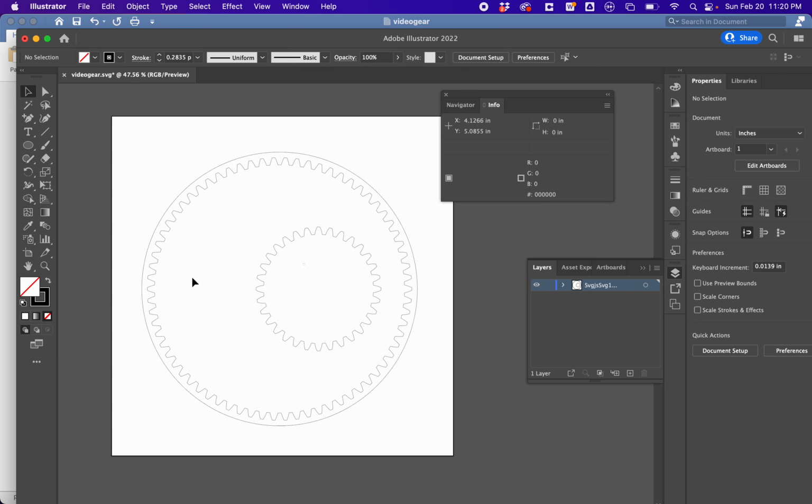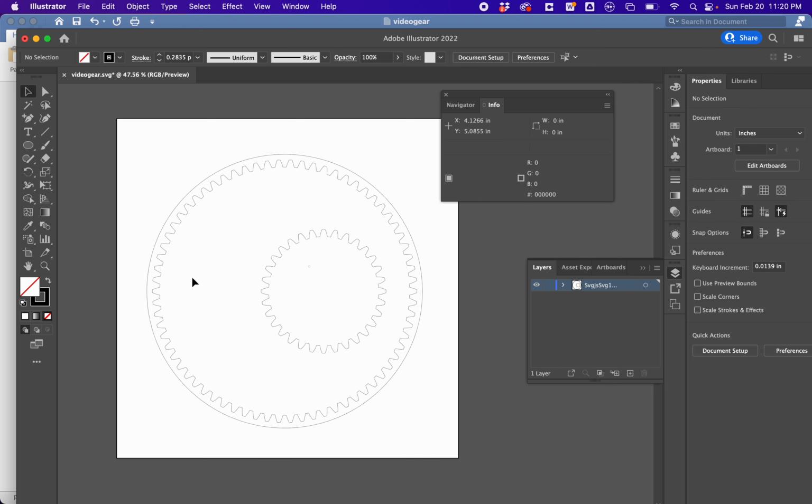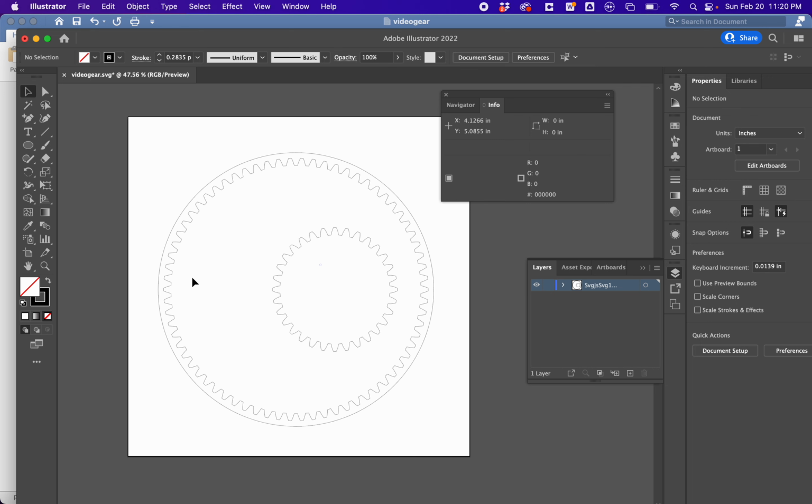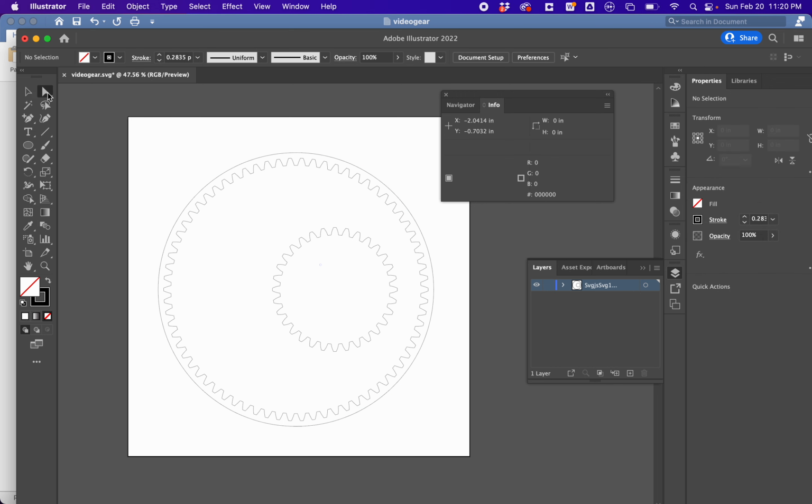One last thing to consider is that the material we are using is not going to be extraordinarily thick. It is wood. It's a little bit flexible. If your outer gear is looking a little thin, as I'd say this one is, we're going to want to perhaps stiffen it up a little bit by making this outer ring a little bit thicker. So we're going to leave the teeth exactly where they are.